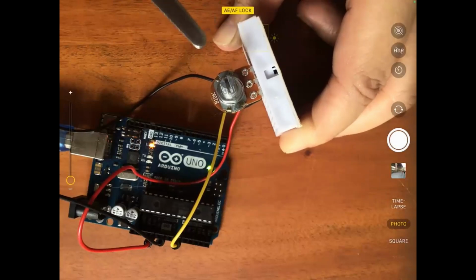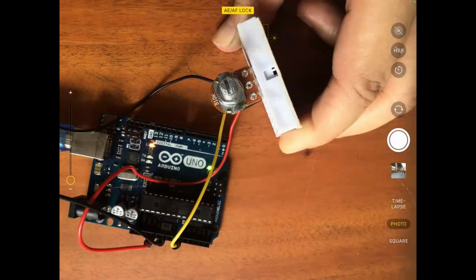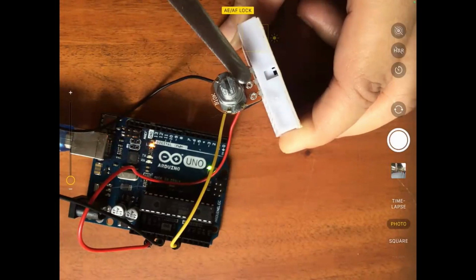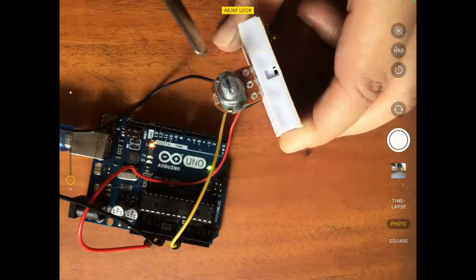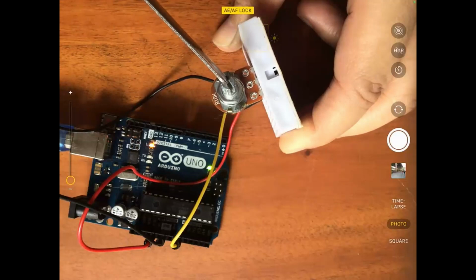So, ang gagawin nyo is, kung may printer kayo sa bahay, download yung template ng protractor, 0 to 360. Print it out, cut it out, put it on a stiff board, and figure out how to attach it properly dito sa may shaft. So you get a stick, can be a popsicle stick or any thin board that can fit this shaft, okay? And then, make sure na dun sa sagad na sagad niyang setting, yung 0, kunyari, naka-align yung 0 degrees ng potentiometer. And then, start tabulating.